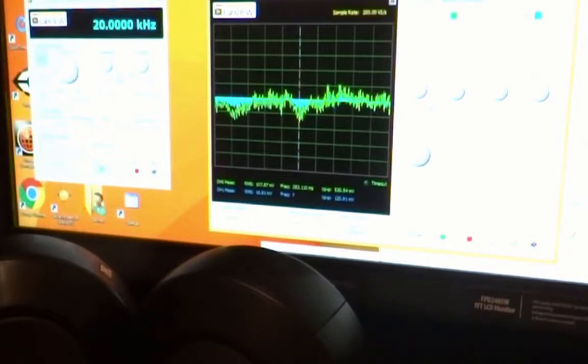So I had it 200 here and 100 here, a difference by a factor of 2, because going through the AM modulation process, when you look at the Fourier transform properties associated with that, basically the signal gets divided in half. There's a 1/2 that shows up from the math. And so by putting the scale down to 100 instead of 200, I was able to plot those both evenly, on the quote-unquote same scale.